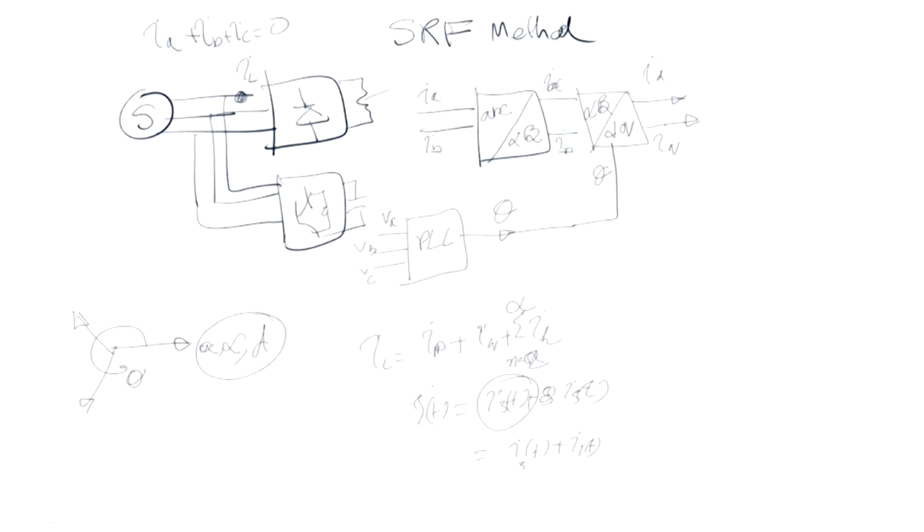So, I can say the original load current in the DQ frame will come as the average value ID, and the IQ part in ID will be of course 0, and these harmonics will come as a delta. I can write ID, that corresponds to the in-phase component of the voltage with the current, and similarly you can have IQ delta plus IQ bar, that is essentially the average, which will be a constant value.